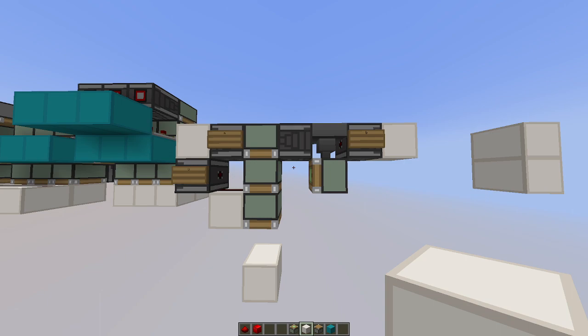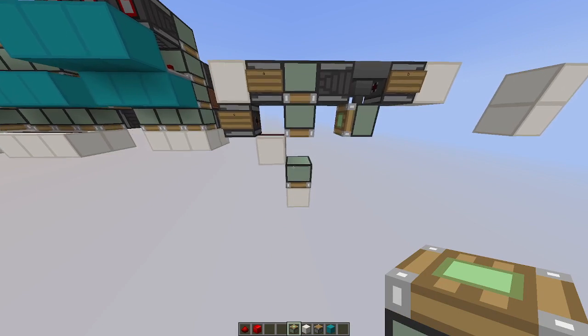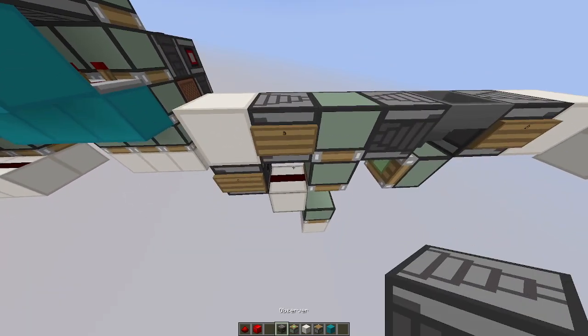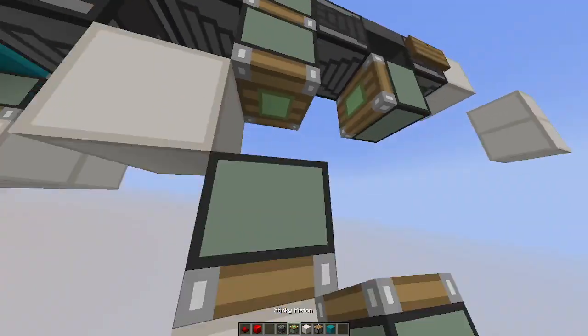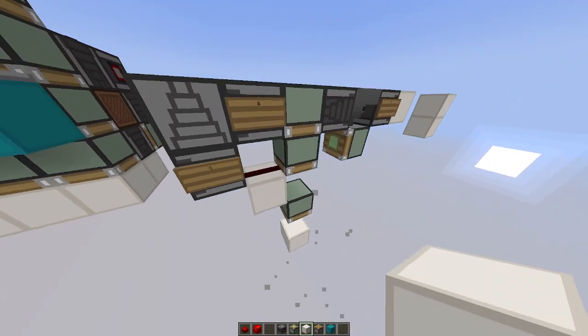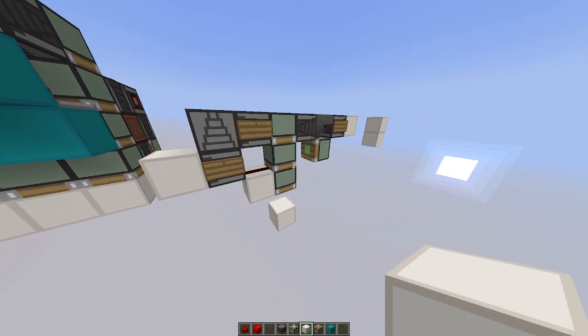What we can do is that we can use timings. So, how should we time this then? Well, a nice solution would be to have, for example, a delay circuit like this. So let's just see how it works. So this will grab its block, and then A will power the middle piston actually, like so. And the reason, again, is due to racing condition. It's that simple. So just revise your piston powering properties and you will already know why.